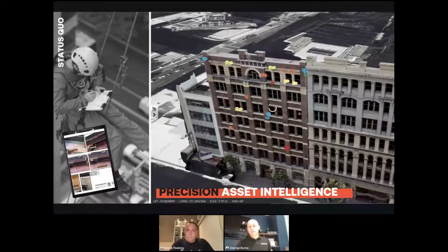So Derek, what would that mean for the end client if those defects are missed, or if they're marked up incorrectly? If we take this facade, for example, we've seen where defects have been marked up on, say, drop 1, level 4. So they'll send a maintenance contractor out to fix some spalling or a loose brick. But when they actually set up abseil down to repair it, it's not there. It's level 2, drop 2, level 6. So they have to go back up.